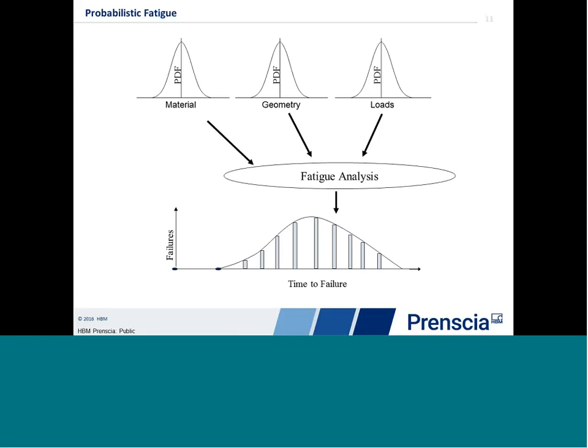And this becomes very important for us when we start to think about how we prove or demonstrate characteristic life values, like our specification just a minute ago said, we need to show 90% reliability and 90% confidence that parts will be free of cracks. 90% of parts won't have cracks in them. We have to be confident in that as well after 4,000 service hours. So this is some statistical background. Now we've got to think about how we tie these statistics into the way we define our durability test.